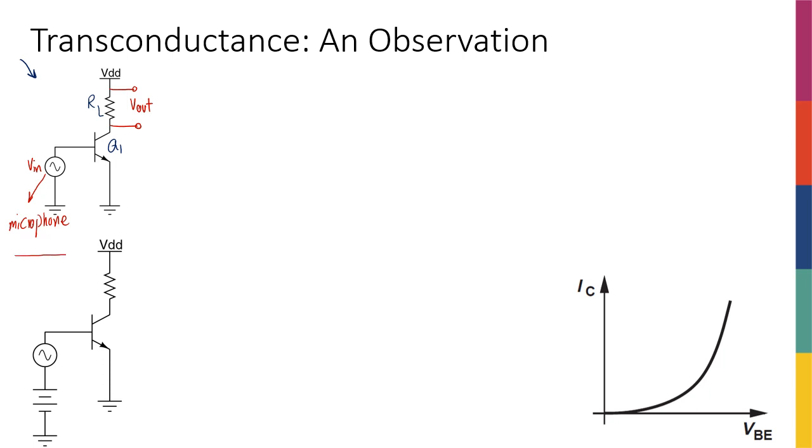And if I have any kind of sound, depending on the magnitude of the sound, it's going to generate some signal that is up to, I don't know, 10 millivolts. So from 0 to 10 millivolts, depending on the magnitude of the sound that is played into the microphone. Meaning that the voltage that appears at this node, at the base of my transistor, is going to be somewhere between 0 and 10 millivolts, depending on the volume of the sound.